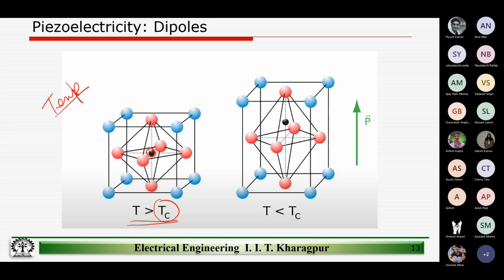So when we are designing or manufacturing the material, what should be the goal of the engineer to make the Curie temperature? Should we try to keep it low? And the physical significance I've explained, we are talking of this in the context of piezoelectricity. It's very important to remember that we are in the instrumentation device class and we are talking about piezoelectric material.